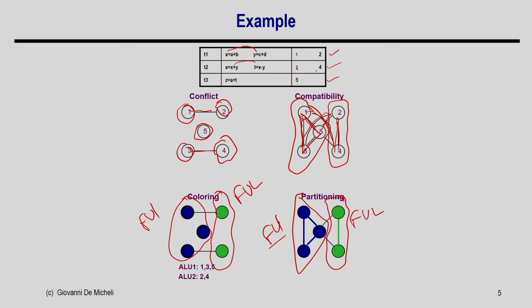So, this is how we have discussed the problem can be mapped to either the clique cover problem or the graph coloring problem. Then we found that in general the graph coloring or clique cover problem is NP complete. That means we do not have an efficient algorithm, that means a deterministic polynomial time algorithm, to solve the problem. So, usually we go for heuristic algorithms.